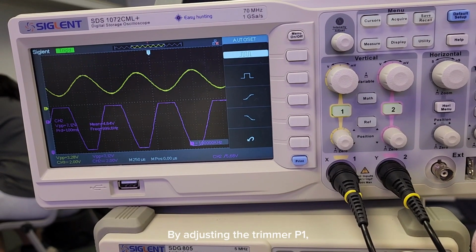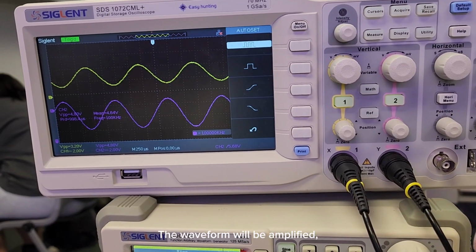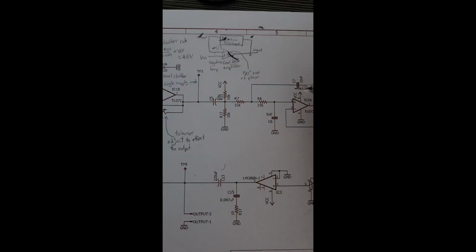By adjusting trimmer P1, the output waveform will change. The waveform will be amplified, but will be saturated and cut off at a certain point.